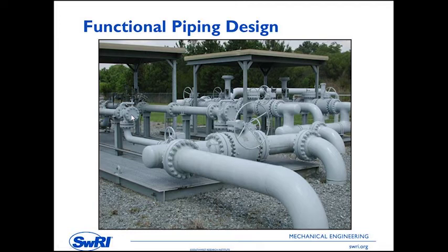The concern that I had with this site was that this 4-inch showed extreme turbulence. If we take a look at, and this was the other end of the meter tube. Once again, tees, elbows, close coupled, lots of turns. A very noisy situation.